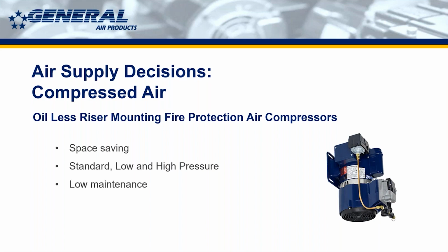That's why it's important to get it right from the design stage all the way through, so that somebody doesn't go and try to put a standard pressure compressor with a low pressure valve and then start adjusting the pressure switch. It's really just going to cause nothing but problems.